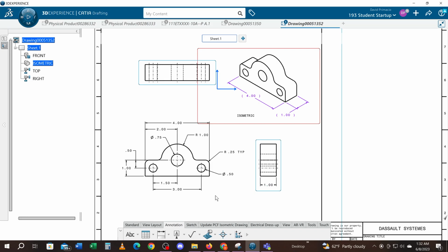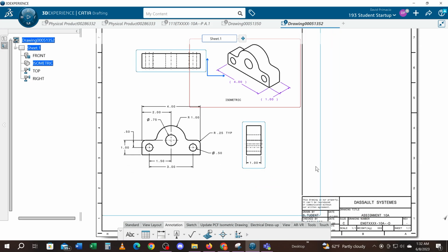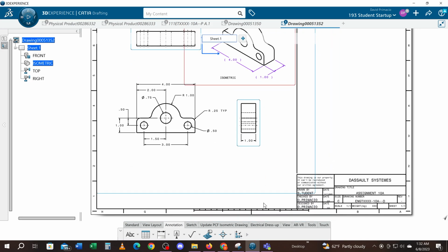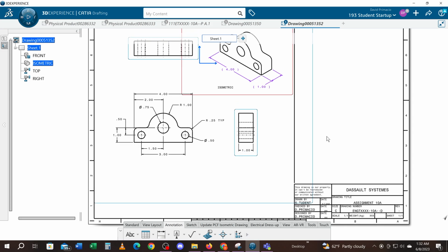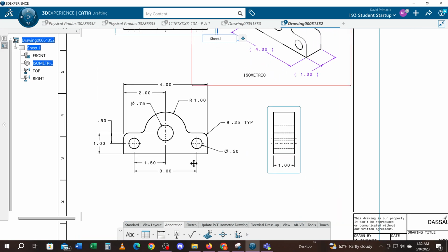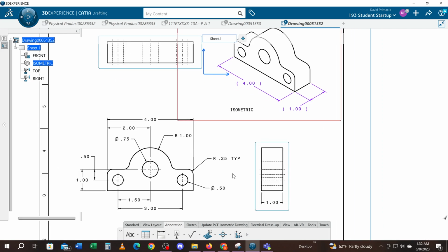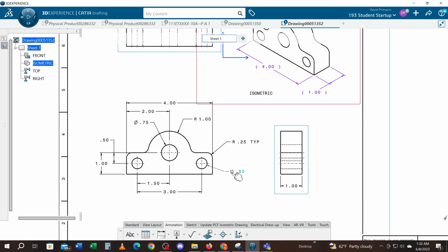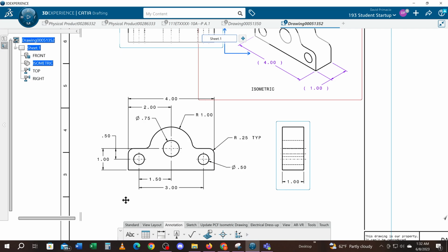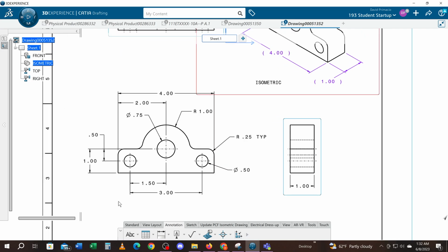At this point, you should know how to put on the datums on each view, and then put your general notes in your tolerance block, and the flag note for which datums are the most important ones. Go ahead and try it before I do this, and then you can verify you did it correctly or make fixes accordingly. So pause the video and try it.